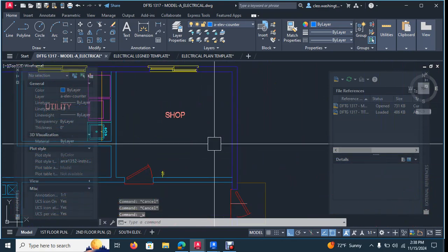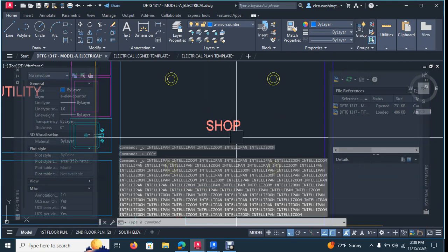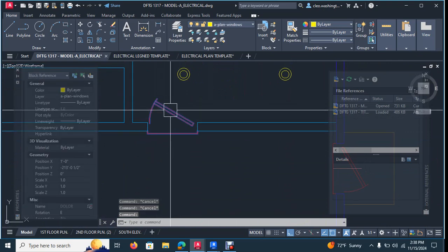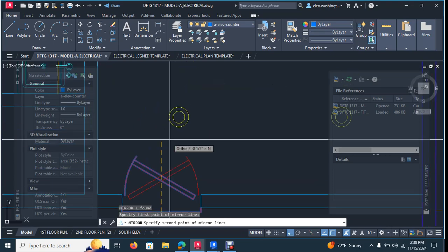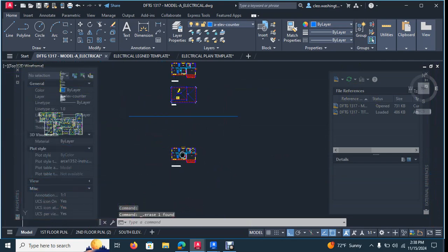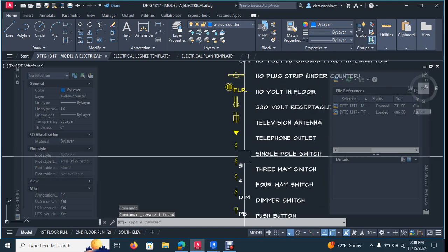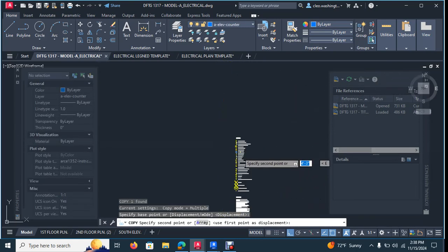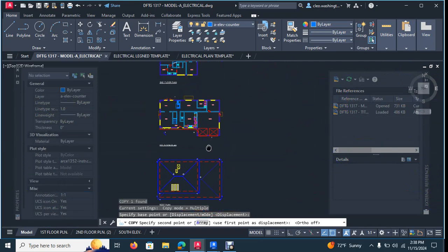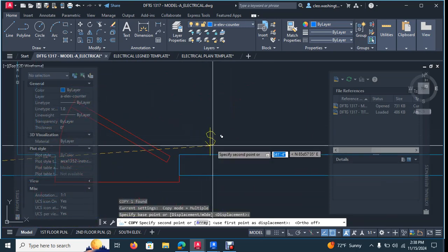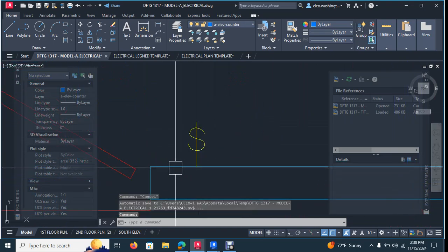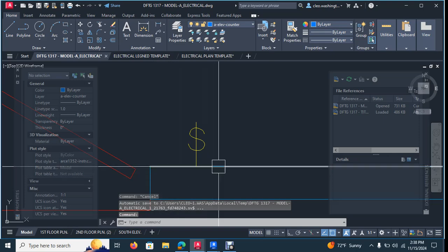And what happened to I deleted something, right? All right, let's do this again. Select the door, MI, pull it up, enter. Let's delete this old one. Now let's go over here and grab a switch. And let's place that switch right on the wall, okay? Typically, you don't want it to be right to the door. I typically like to go anywhere from 6 to 10 inches, all right?